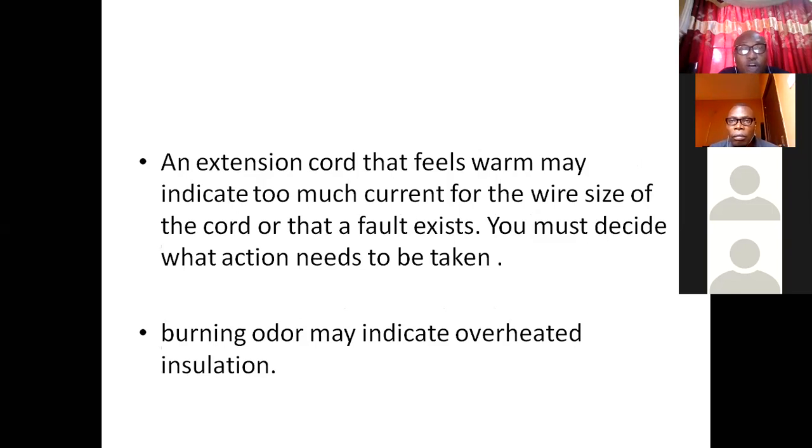You want to use an AC, and you are using a flexible wire for an AC, or you are using a wire that is like one wants to kill itself. Or the electrician says, "Oga, you have to buy 15 amps for this." "Okay, I don't have 15 amps. Help me to manage 10 amps," and you want to use it for AC. You can see that the amperage does not correspond to the power of the AC, so you need to use something higher. Evaluating will let you know that this wire is too short, or it cannot carry the size of this thing.